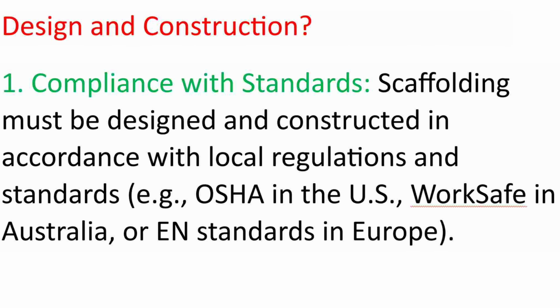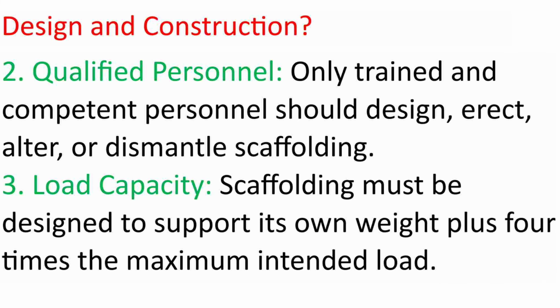Question: what is the design and construction? 1. Compliance with standards. Scaffolding must be designed and constructed in accordance with local regulations and standards, for example, OSHA in the US, WorkSafe in Australia, or EN standards in Europe. 2. Qualified personnel. Only trained and competent personnel should design, erect, alter, or dismantle scaffolding. 3. Load capacity. Scaffolding must be designed to support its own weight plus 4 times the maximum intended load.